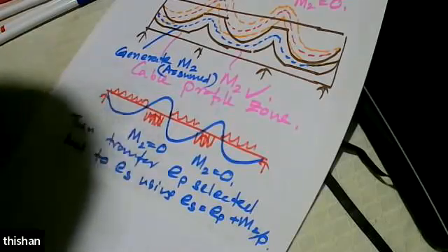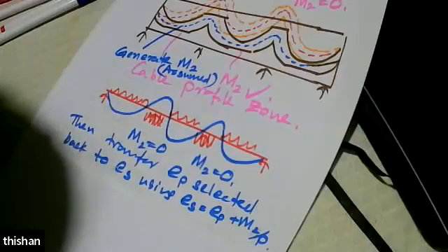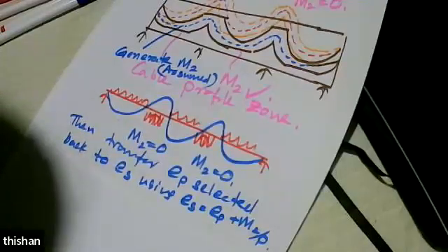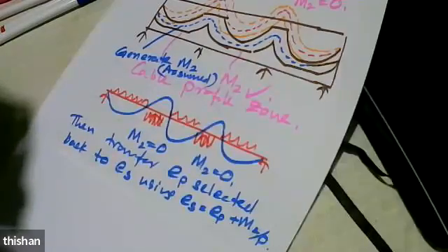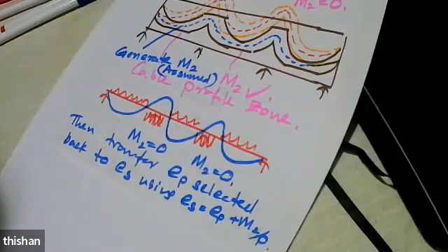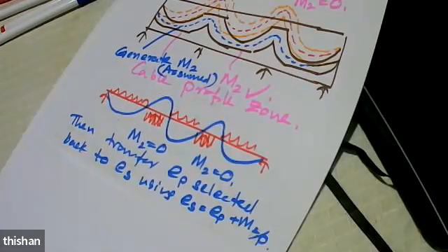And then there's something called concordant profile, which you can also find in any textbook. The concordant profile is a profile that does not generate secondary moments. Linear transformation is finding a line of thrust from a cable profile. So those are standard methods.